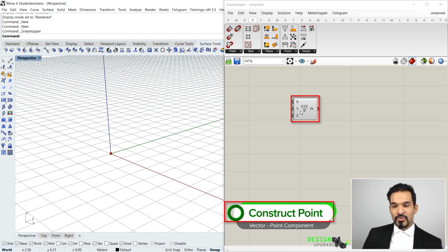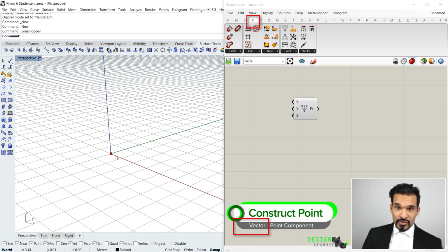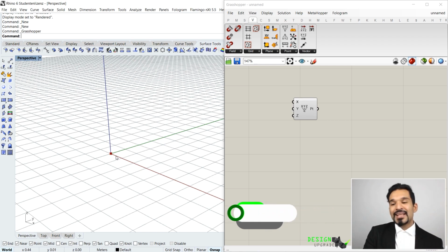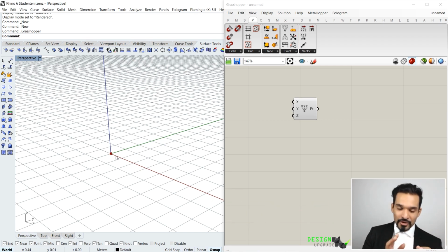Baking is a process where you take geometry from Grasshopper and you then internalize it in Rhino so it can be used there. But then obviously you can't edit it anymore in Grasshopper. Once it's baked, it's finally as a hard copy done in Rhino, which cannot be modified. In the normal basic setup, you can always do that, but in a normal sense, no.